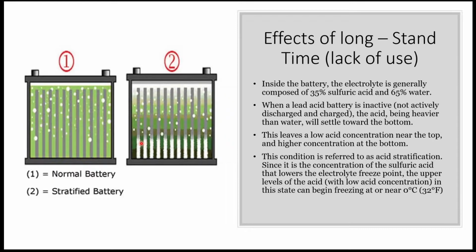Inside the case of the battery, if it's an SLI battery, there are supposed to be some chambers at the bottom that allow for sediment to settle as the plates degrade and shed the excessive coatings on the outside of the plates. That mineral content that sheds is supposed to build up in these little compartments down here and not affect the shorting out of the plates. But as you let it sit and the battery is exposed to the up and down temperature variation of the concrete, the minerals start to settle and it starts to bring the battery down to its knees.